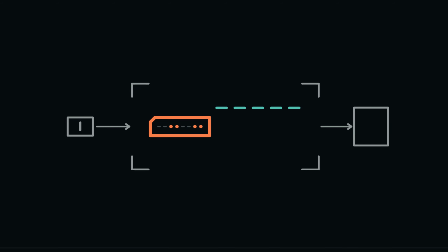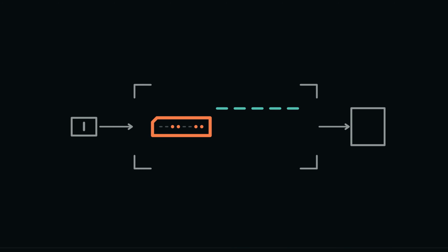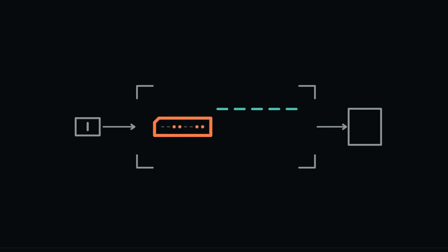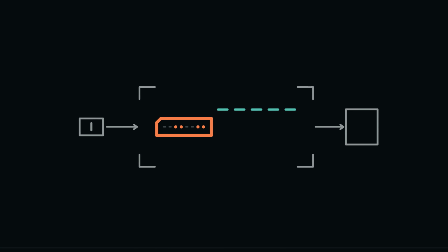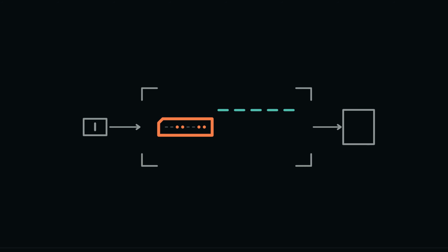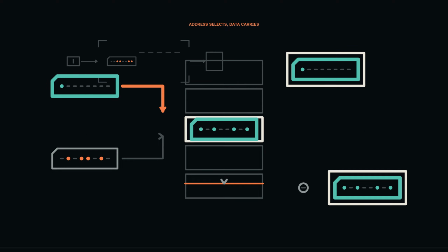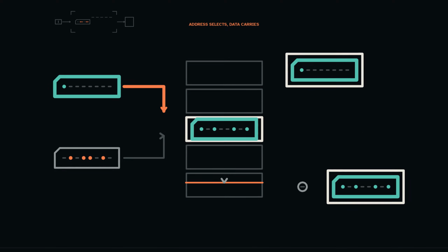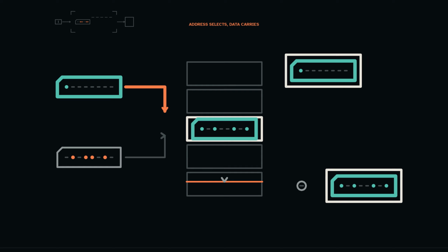MAR holds its previous address, MDR holds its previous byte, memory location hexadecimal 80 holds hexadecimal A5, and source register R2 holds hexadecimal 5A. We will write 5A to address 80, then read it back, without allowing any intermediate value to vanish. First, the operand address hexadecimal 80 drives the bus, and MAR is selected to receive.